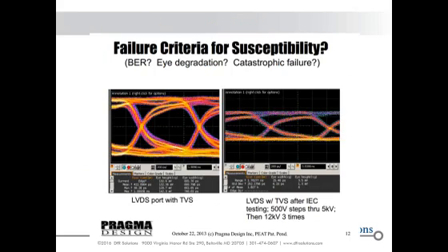You look at the next one, which is about failure criteria. When we have functional changes for upsetting the system, and it either hangs or corrupts the display or things like that, those are soft errors. But when we have hard errors, sometimes it's not as simple as seeing a big hole on the silicon later on where ESD damage is visible, but it could be something between a latent and a physical visible damage, where the leakage is not apparent at DC, but it may be apparent in high frequency domains,